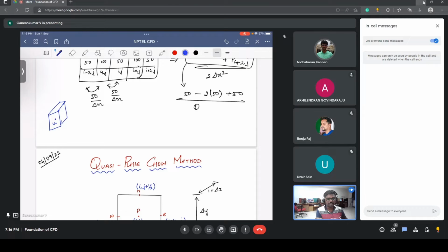You have a continuity equation and a momentum equation where density is constant, because it's an incompressible flow. There's going to be ∂u_i/∂t plus a convection term, a diffusion term, and a pressure gradient. Now, this pressure is not related to density. Density is going to be constant in our incompressible flow. So these two equations are fully decoupled from the energy equation.